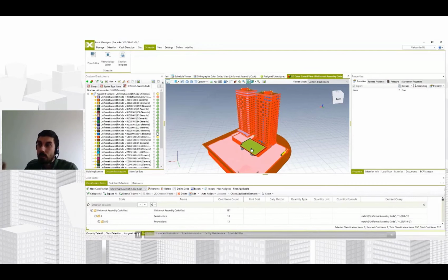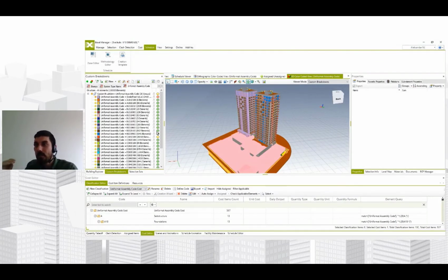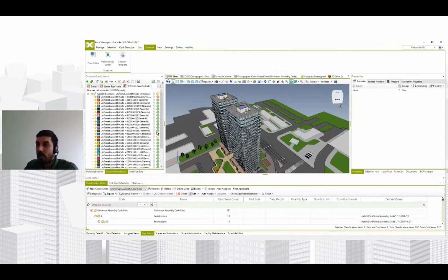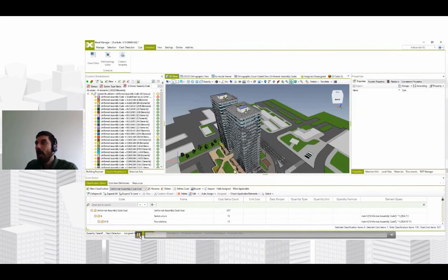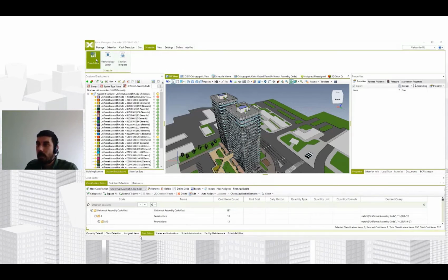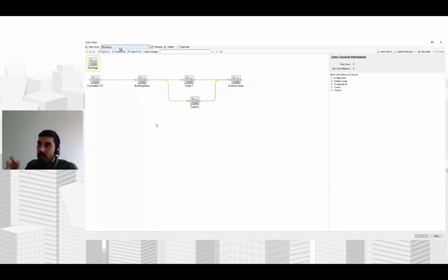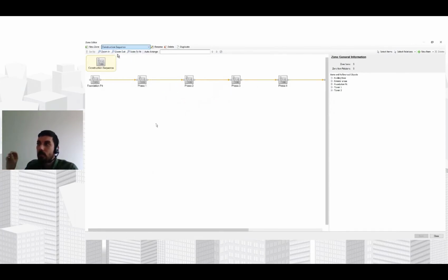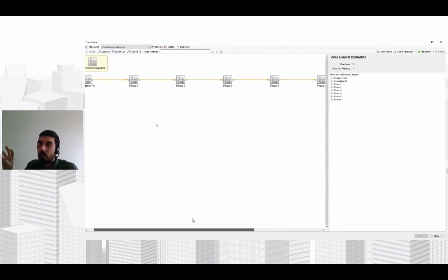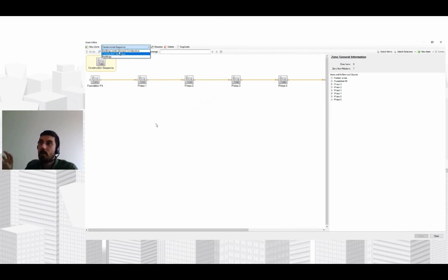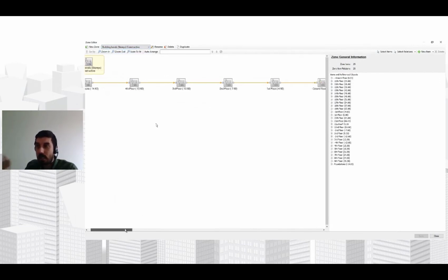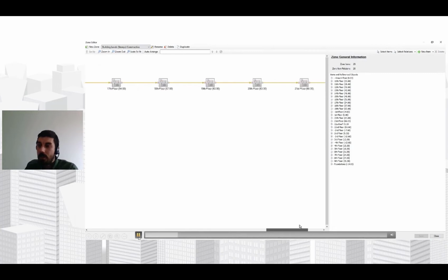Of course, we also have this uniform coding system. We have cost classification, so based on this, we can create the work sequence organization for our schedule. So how this looks in practice, within what we call a zone editor: the user is just creating the zone items and relating these zone items or nodes to the information in the model, to the information about the phase of the elements, about the building in which the elements are placed, about the floor on which the elements are placed. And all of this information is present in the model by default.